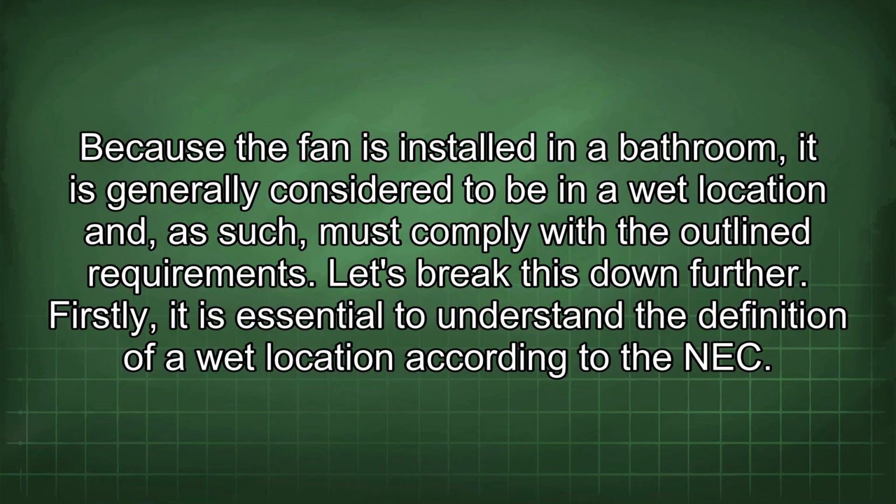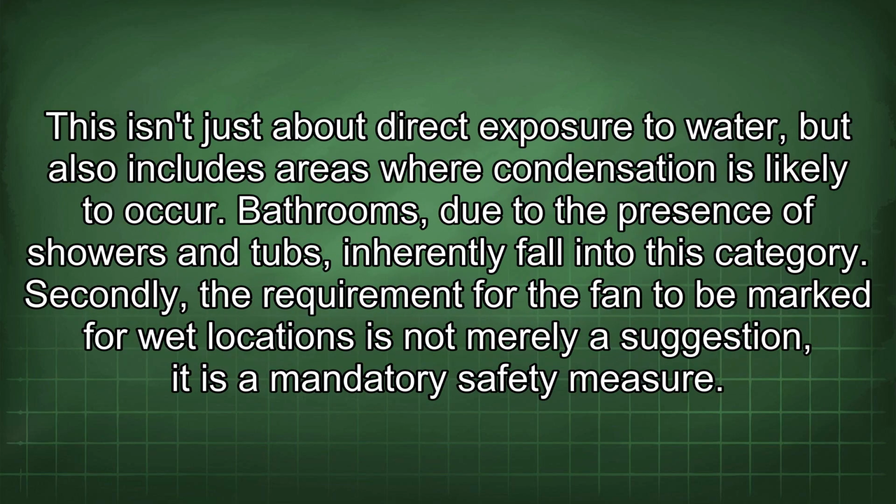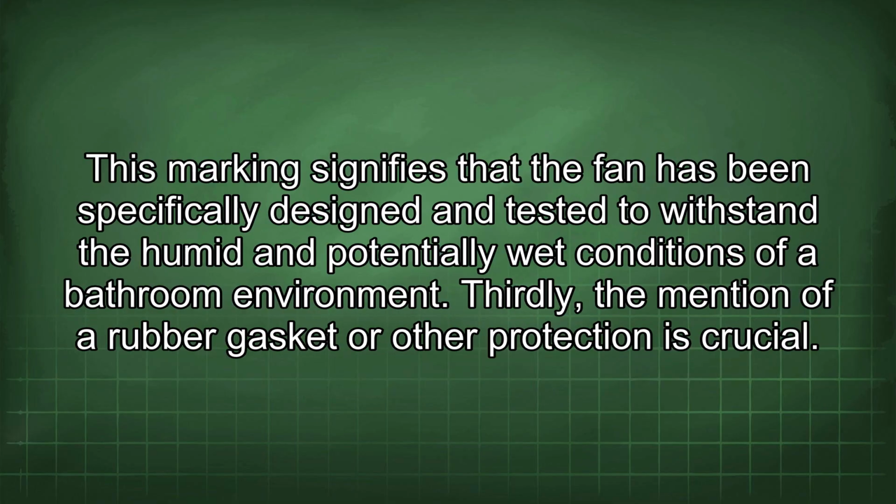Let's break this down further. Firstly, it is essential to understand the definition of a wet location according to the NEC. This isn't just about direct exposure to water, but also includes areas where condensation is likely to occur. Bathrooms, due to the presence of showers and tubs, inherently fall into this category. Secondly, the requirement for the fan to be marked for wet locations is not merely a suggestion, it is a mandatory safety measure. This marking signifies that the fan has been specifically designed and tested to withstand the humid and potentially wet conditions of a bathroom environment.